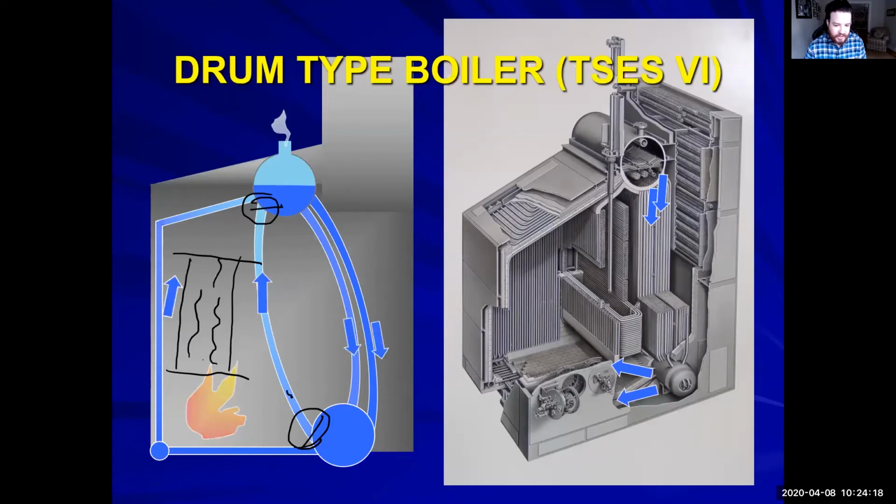So as the steam bubbles travel up the generating tube, they're going to be heated up by this flame. But what else are they doing? What are they surrounded by? Surrounded by more water that's lower temperature. So as it travels up, it's heating up the water that's surrounding it. So you may have a steam bubble that travels an inch and then turns back into a liquid, giving off its energy to other water around it. Maybe you even have a little bit of circulating steam bubbles that are just happening in these little spots, where they become steam. They start going up through the water faster. And then as they go up through the water, they give off their energy, and then they become water again. So they slow down, they start to become water, and they fall off basically.